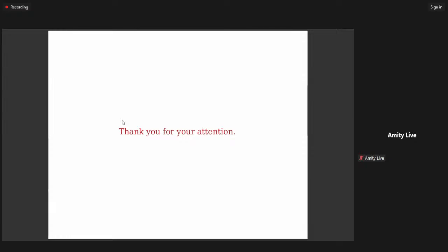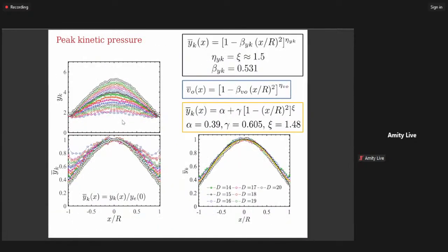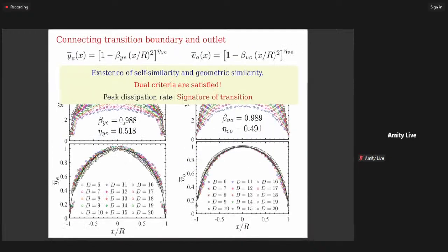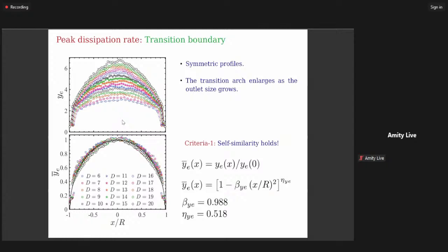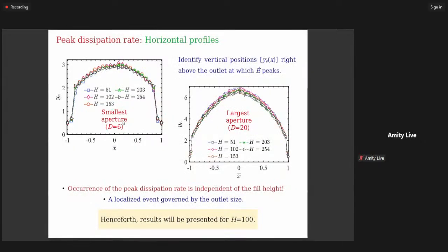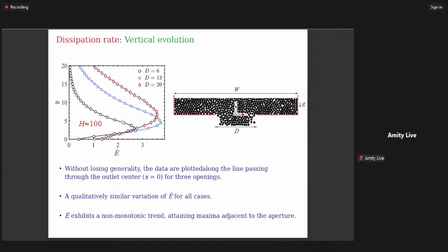At the outlet, velocities are very high. So how is it near the outlet? You said it is an energy sink. Yeah, energy sink. It means the energy dissipation rate is high, so it is losing the kinetic energy and basically velocities would come down. No, velocities are increasing. I'm contradicting something? No, velocities are high near the outlet. That's what I said, because if you look at energy dissipation rate,